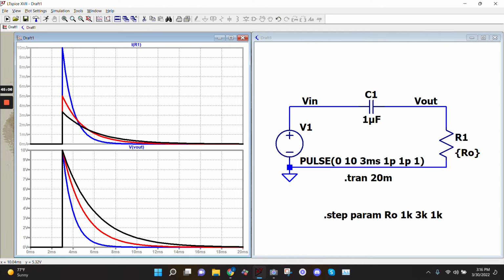Yeah. So it's basically what you're showing us with capacitors right now is that the order of where you have your voltage, your capacitor, and your resistor matters. If you have a voltage, resistor, capacitor, then it's going to be charging, and if it's capacitor, resistor, voltage, it's going to be discharging. For finding V out, if you're talking about this particular node, then yes.